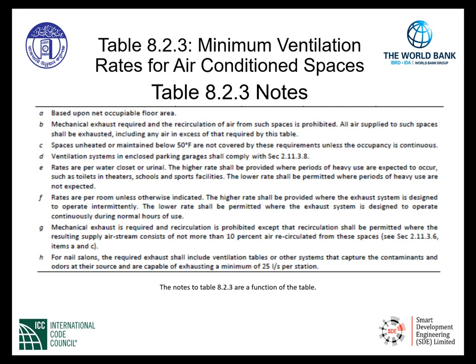It means a local exhaust system capable of exhausting 25 liters per second per nail station. That's a specific note. And as you can see, all of the other notes are pretty important with respect to different areas within our buildings.